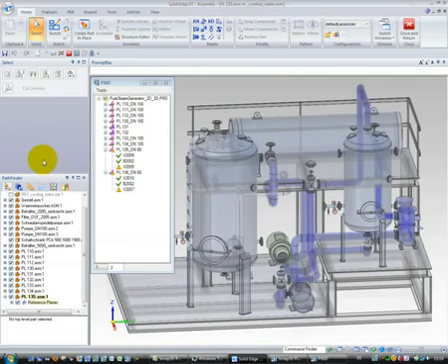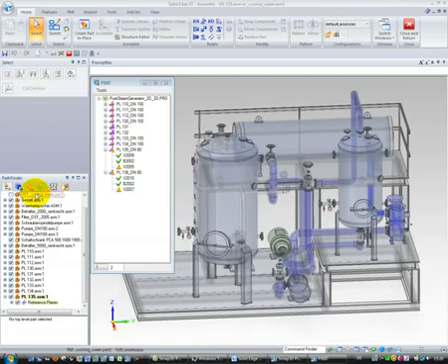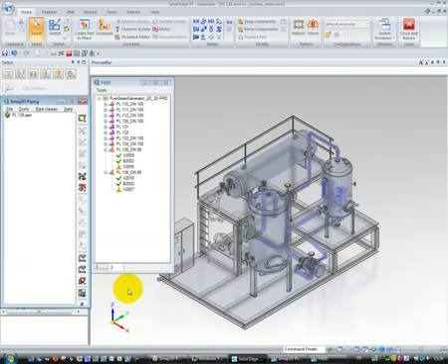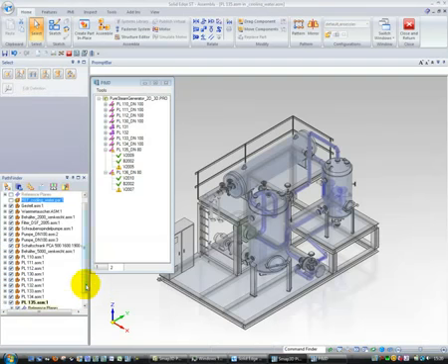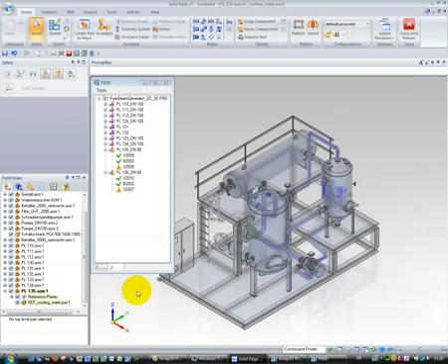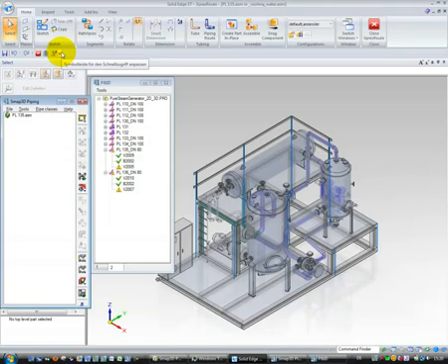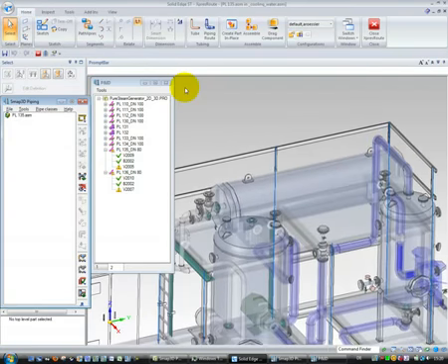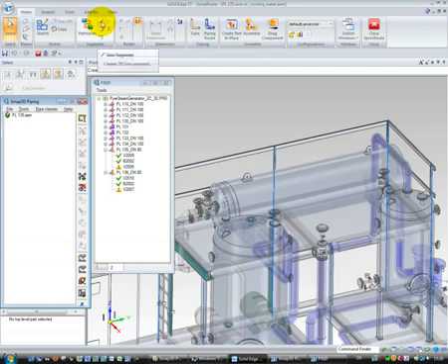Now I'm in the subassembly and I need access to the connection points of the environment components. This we realize by copying a reference component where all connection faces are included via interpart copies. Now we start drawing the pipeline paths. For this we switch to the express route environment, and there we start the drawing functions. To draw the path we have several possibilities, for example to draw single line segments, or to use the path express.